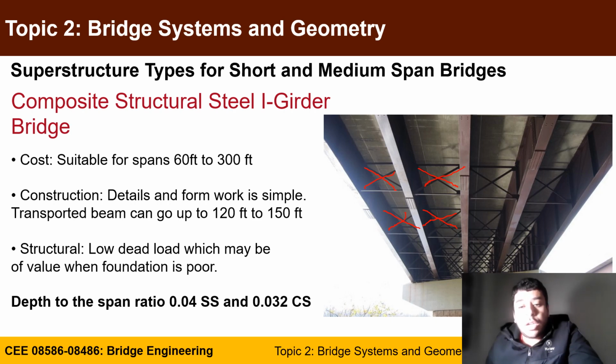And also during the service life of the bridge, it actually helps the girders to work together as one structure for overturning moment or forces. If, for example, the truck loading is concentrated on one side, it may provide overturning, so you need the superstructure to act as one unit and distribute the load rather than loading just the girder that is underneath the truck.